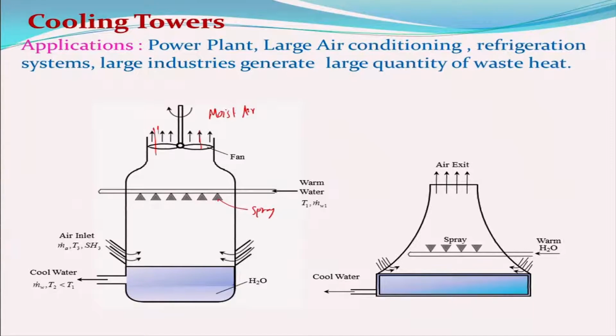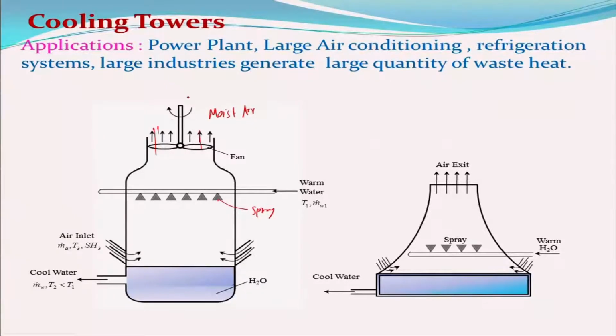As a result, less water will be collected here than whatever is going through. That water difference we call make-up water, because the difference is due to evaporation: some of the water is converted into vapor and carried away by the air. This is where you will have to give some power, you will have to use some energy for that.